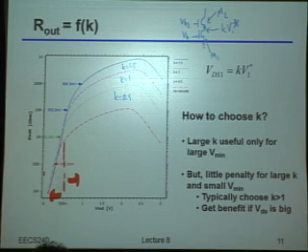So again, the perhaps somewhat surprising result, especially if you think of this from a simple long channel saturation versus not analogy, is that you will tend to want to make sure that you have as much bias across that bottom device as you can, simply because that will get you the highest possible output impedance in pretty much all of the scenarios that you can think of. Now, there are some caveats to this when you start thinking about the extra capacitance you're introducing. I'll talk about that more a little bit later on, but do keep this in mind.